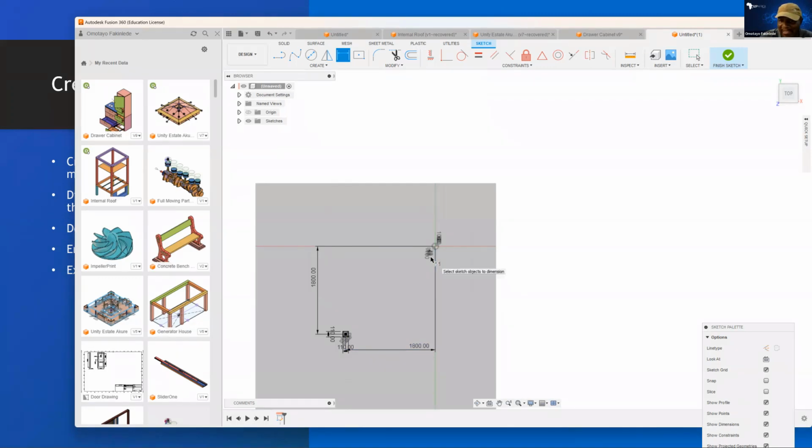But there are 4 pillars, and this is the center. How do I get the remaining 3? There are several ways to do it. I can use pattern replication. I can use mirroring. I decided to use mirroring for this simple case. So I can create a mirror at the sketch level. I create a mirror by choosing the mirror icon, and then it wants me to select objects to mirror. It is what I've created here. That's what I want to mirror.